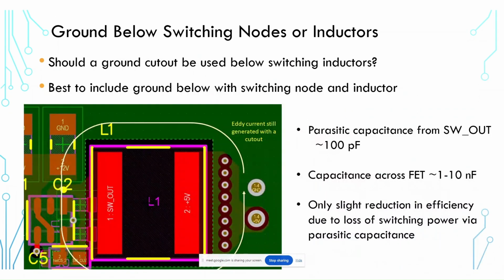So just backing up for a moment before getting into impedance matching networks. One thing I'd like to note is that this is just showing a specific type of inductor. This inductor could be a shielded inductor, so that will also help prevent the leakage of any magnetic field around the inductor. But of course, there are also, for example, toroidal inductors. There are also horizontal inductors, basically wire-wound inductors. This particular inductor is a vertical inductor, but it could be shielded.